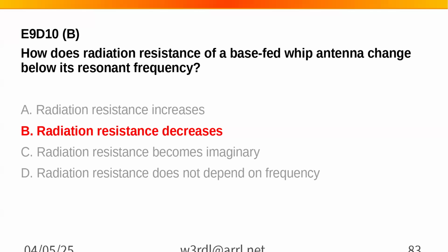Does it become capacitive because it's less inductive? Or does capacitance actually increase? Well, if you remember a few weeks back, it showed those plots of frequency versus the length, and you get to the resonant point, you're capacitive and then inductive. Depending on whether it's series or parallel, because they're opposite.